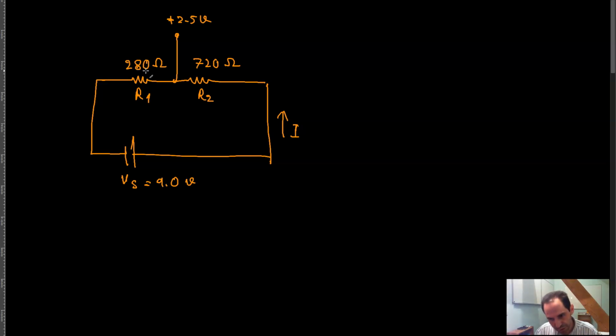Now, since the total resistance changes and the power supply is kept constant, of course the current in the circuit changes, and that current should be something that can be supplied by the power supply, and also that current should be something that can be handled by these two resistors. At the end of the day, some current is going through these two resistors, and the power dissipation capability of these two resistors has to be chosen accordingly as well, right? So all of those things you already know.